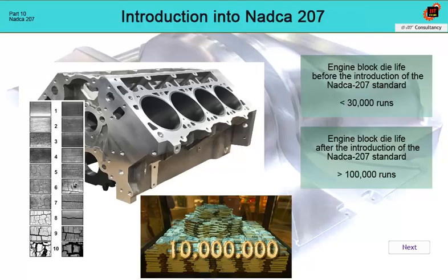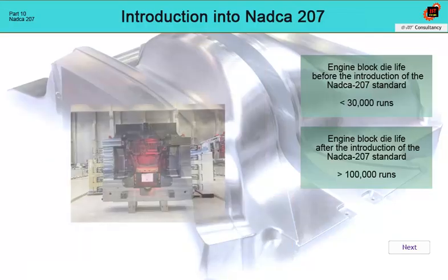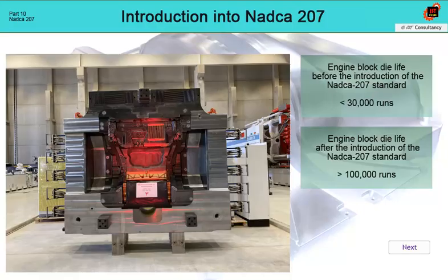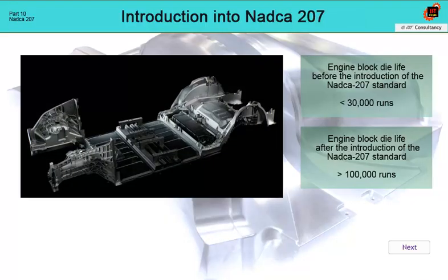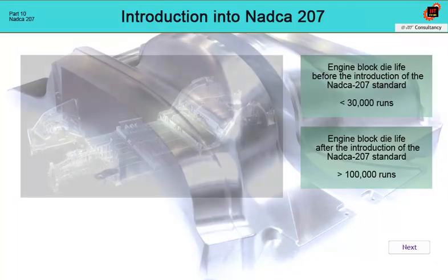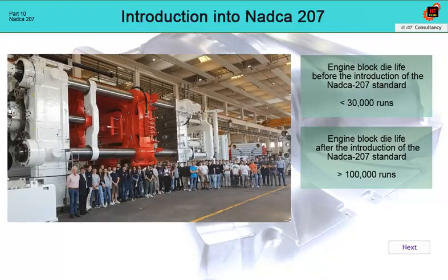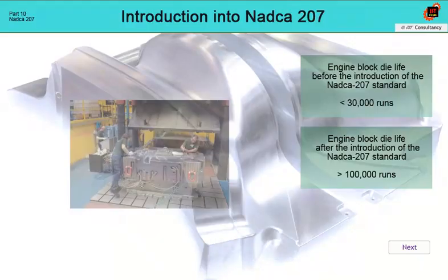A new situation in the technology of die casting, known today also under the abbreviation HPDC, high-pressure die casting, is brought by Elon Musk and his Tesla's revolutionary change to the concept of car production in the gigafactory. The term giga casting is born when the existing several hundred parts of a car are replaced by several castings, produced on giga presses with a clamping force of up to 16,000 tons. The size of the die for die casting is growing significantly, as is its price. For example, the moving part of the die for the rear part of a Tesla car weighs 70 tons, while the fixed part weighs 40 tons.